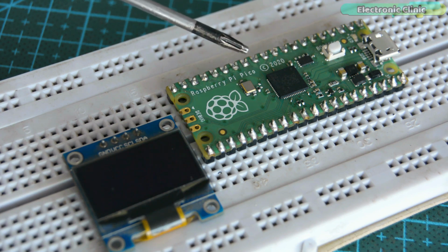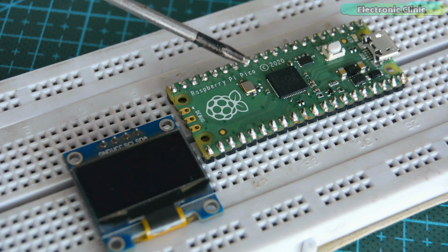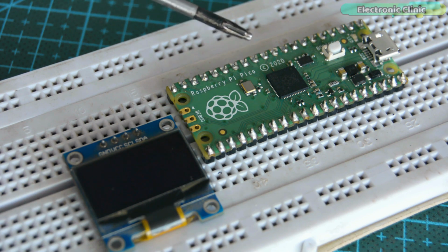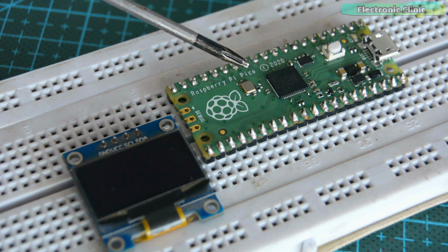But the MicroPython code can scale the ADC values to a 16-bit range, so we effectively get the range from 0 to 65,535. The microcontroller works at 3.3 volts, which means that the ADC pin will return a value of 65,535 when 3.3 volts is applied to it, or 0 when there is no voltage. We can obtain all the in-between values when the voltage applied to the pin is between 0 and 3.3 volts. Let's take a look at the code and you will get the idea.